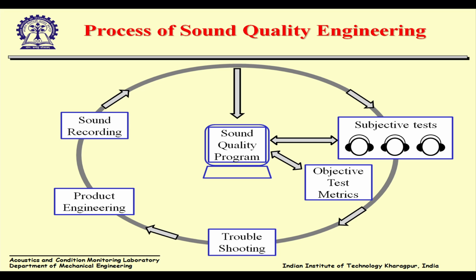In the same way, for sound quality engineering, the strategy is that we vary different metrics, which are not only the decibels but also A-weighted decibels, loudness, sharpness, roughness, and fluctuation. I'll be discussing these metrics individually, but these are the commonly used psychoacoustic or sound quality metrics. The aim now becomes not just to reduce the decibels, but to manipulate or change the other sound quality metrics, and then see that we have changed it and improved the sound quality. Does it correlate with how the users are perceiving it?